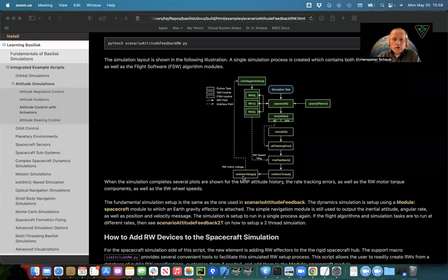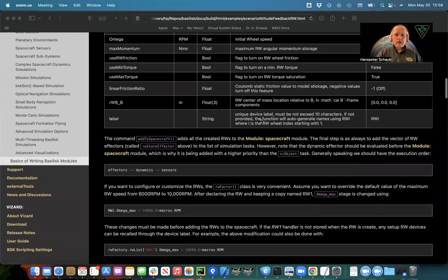And then the reaction wheel motor voltage and reaction wheel voltage interface are optional modules. There'll be a simulation flag, because we can take those motor torques and directly control the reaction wheel torques, which have been added to the spacecraft, or we can create a digital to voltage interface. You can specify voltage behavior and then send a voltage command to a digital to analog interface that turns it into an actual torque command, a voltage, and then that's what drives it. So we'll see both. There'll be a few if statements in there. And when you run it, there's a bunch of flags setting up reaction wheels.